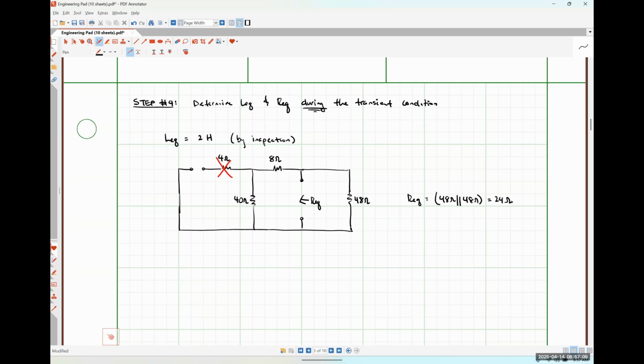Yeah, we take the resistance out and try to find the equivalent inductance at two terminals. Yeah, so if we take the resistance out, it's going to leave behind an open circuited set of terminals. Those are the terminals that we look into. Just like how we took this inductance out, leaving behind an open circuited set of terminals, and those are the terminals we looked into to find REQ.